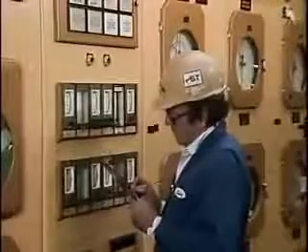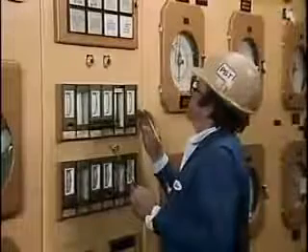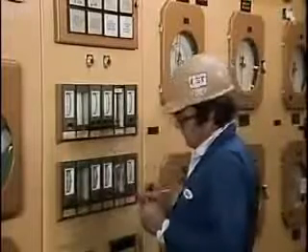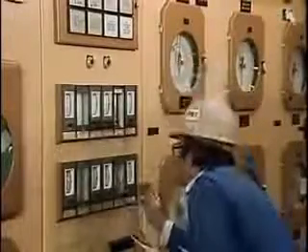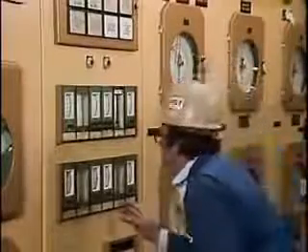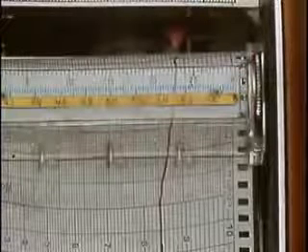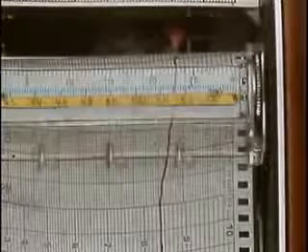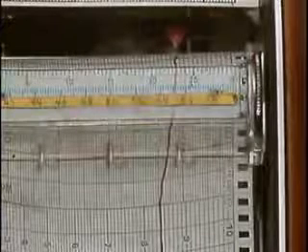Other indicators can also help identify compressor problems, so they should be checked frequently. In many facilities, indicator readings are recorded on a log sheet on a routine basis. These records are important because they can be used to spot abnormal trends, which can indicate that a problem is starting to develop. For example, a steady increase in the compressor's cooling system temperature may be an indication of a problem.